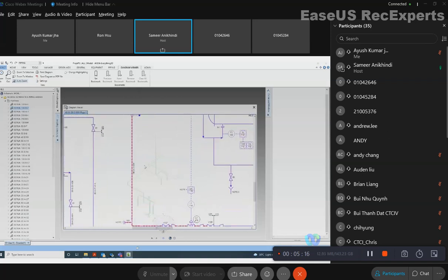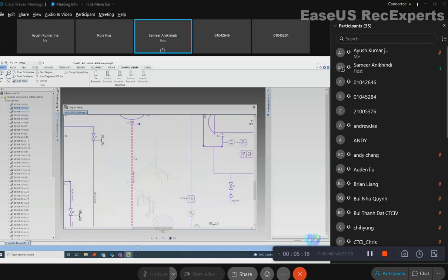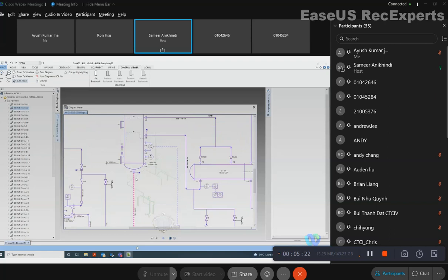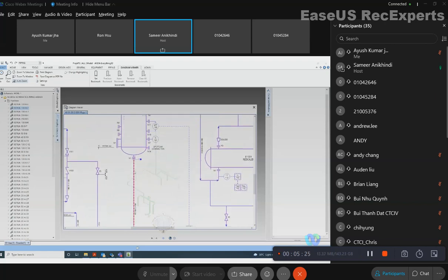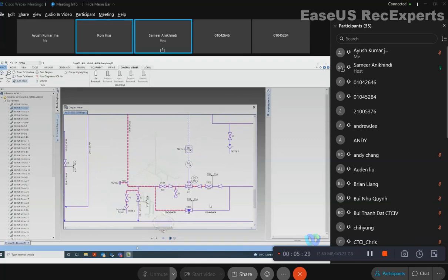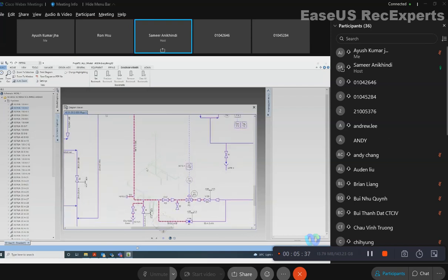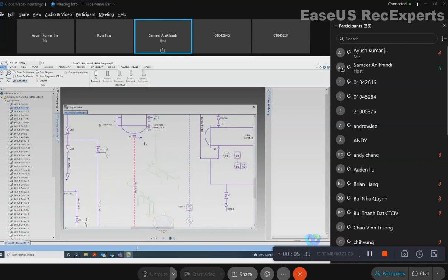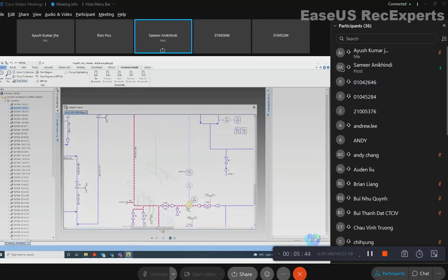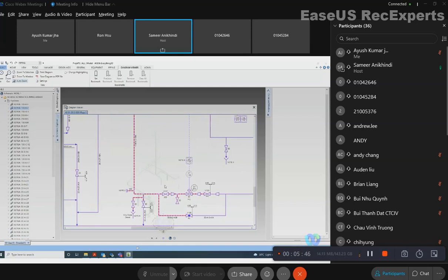So as you can see, this pipe is coming from column C1101 from the bottom nozzle, the N1 nozzle, and it goes into another pipe over here, ATB2, then continues to ATB3. So wherever it finds a model reference, for example this nozzle, it will connect to that. But wherever it does not find one, it will just model the end components.